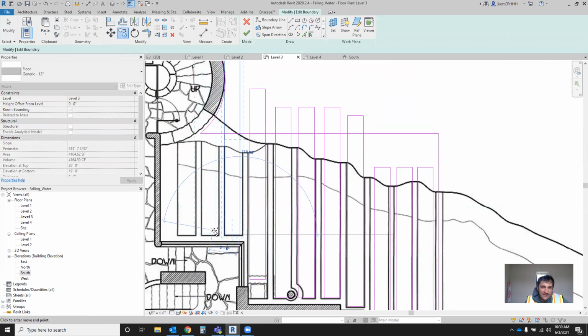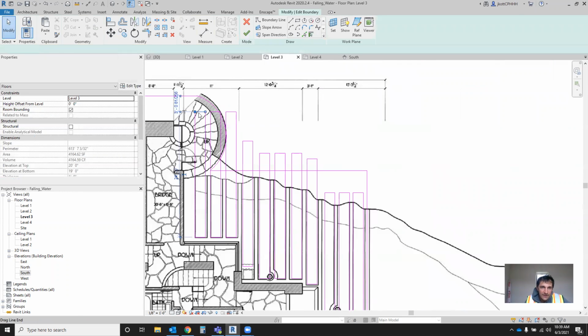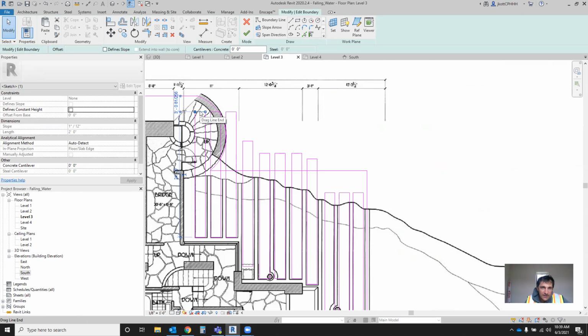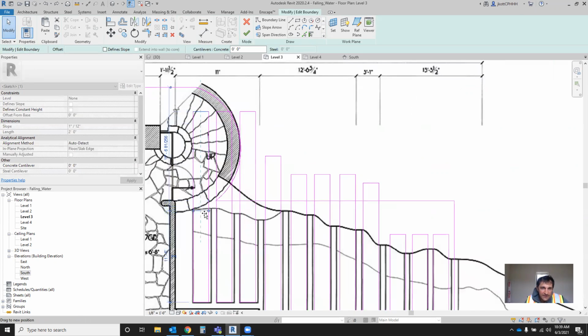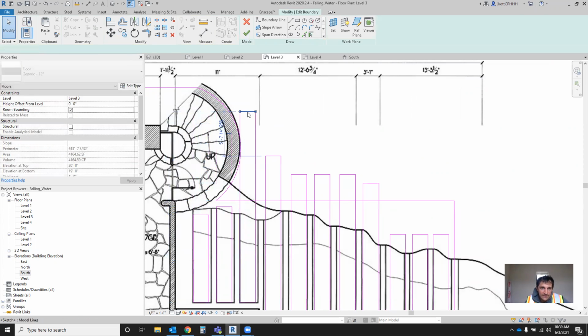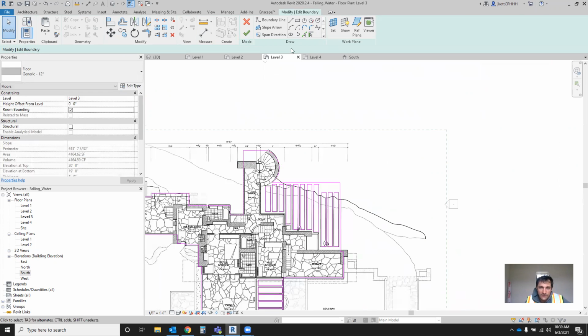These are good base drawings. I think they give enough information for you to model all these pieces that we have here. And we just need to move these elements out of the way of the edge of the floor line like this. We're going to adjust the edge of our topography to match up with this later, but for now, model the floors and walls to the best that you can so that we can start to work on developing this further.